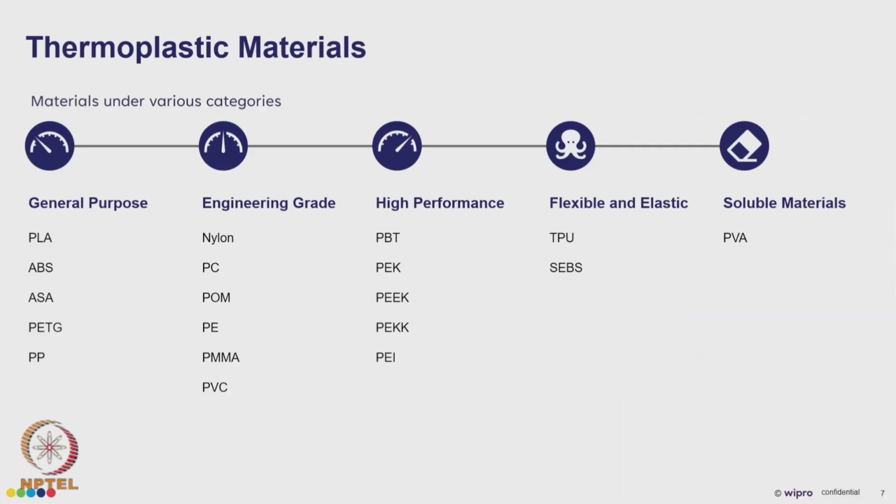Then we have a material called PVA, that is polyvinyl alcohol, which is a soluble material and it is mostly used for PLA kind of materials because its temperature is limited to 180 to 200 kind of temperature. So, it is very easy to get it printed along with PLA kind of material. And we have HIPS, which is called high impact polystyrene, and this material is soluble in limonene kind of solutions. And then we have BVOH, that is butadiene vinyl alcohol copolymer.